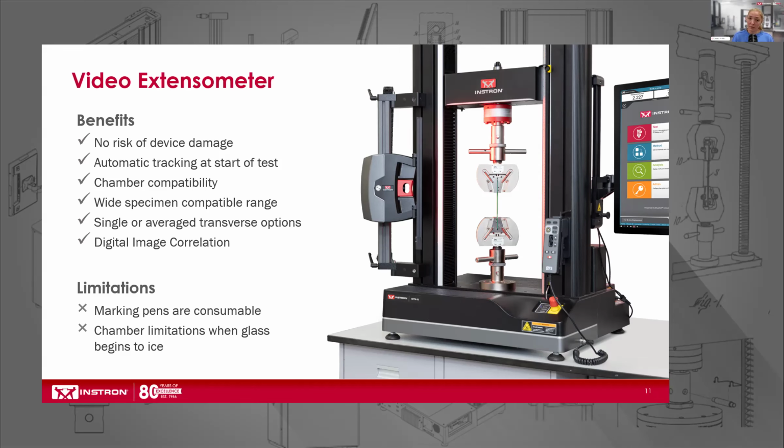When you kick off a test with the AVE, the device will automatically detect the gauge length that you've marked at the start of the test, and it will track that through failure. So this feature could be a nice alternative in those risky situations like composites testing, where if you were using a clip-on, you'd need to retrieve that device while the specimen's still under load. A non-contacting option eliminates that safety risk and prevents you from having to go back into the inactive load string to get your device.